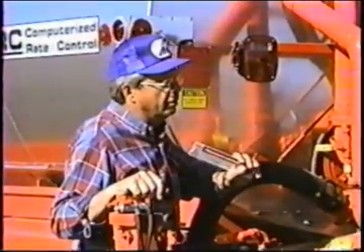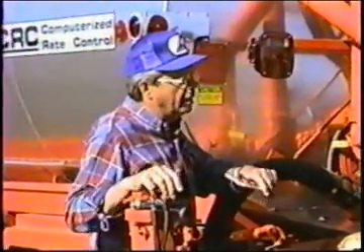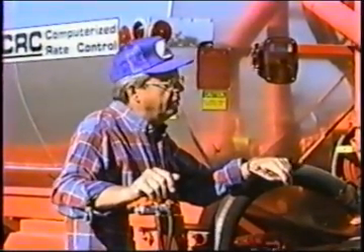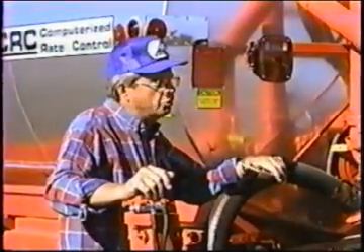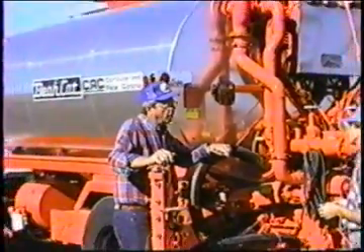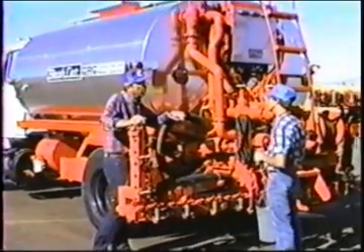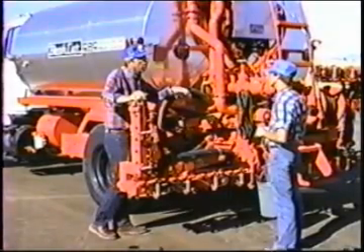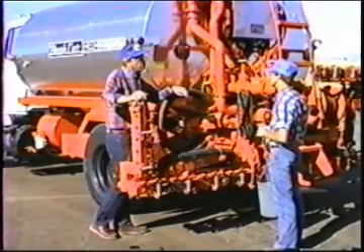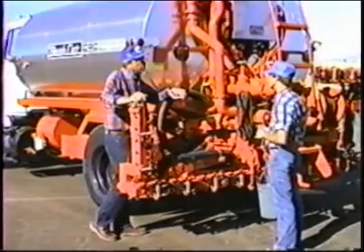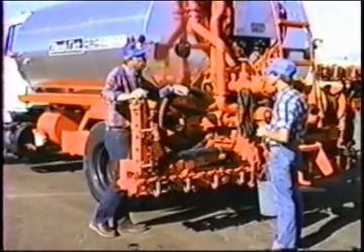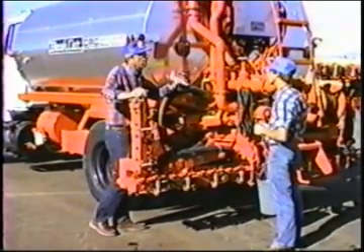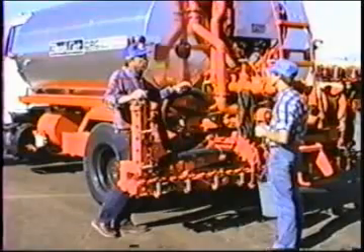They got to tell us, first of all, a desired rate, what they want to put the material down at, because they've ordered material based on that number. And if they've ordered it right, if we shoot that particular spread rate, the material we've brought will cover the job and we won't have any left over. Now, if they've measured it wrong, it's not going to come out right, or if we spread it wrong, it's not going to come out right. Sometimes that's very critical. Well, it's always very critical. It's most critical if you're 300 or 400 miles from home. If you're 300 miles from home and you put the rate down wrong and come up 100 gallons short, that's a long ways to go for 100 gallons in order to finish off the job.